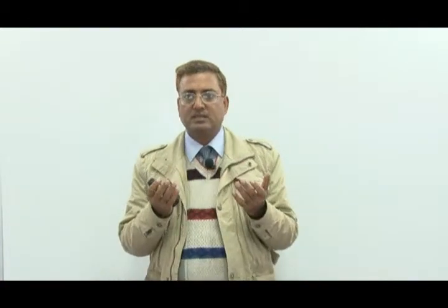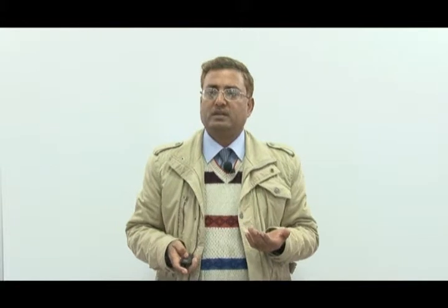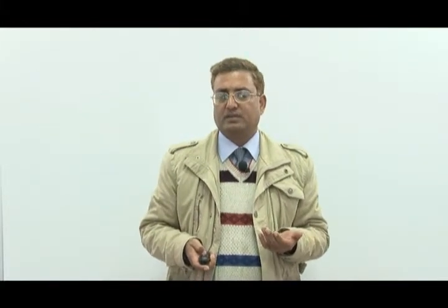So the stresses, that is sigma r, sigma theta, sigma z, and then the shear component tau rz, is nothing but capital E by (1 plus nu)(1 minus twice nu), and that is multiplied by the vector corresponding to strain, that is epsilon r, epsilon theta, and this has been shown in equation 21 here.